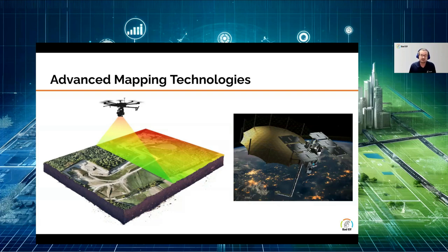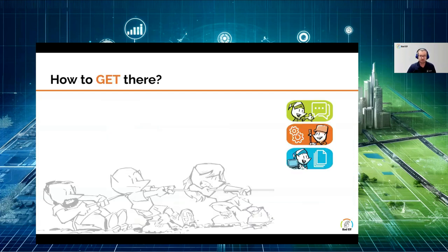I'm just going to highly encourage everybody: you've got to have really good data in to get good data out. So set your ground control, set your GCPs, set that ground reference, and set it up really strong so that all the data that you're producing downstream are coming out the way you want them to.